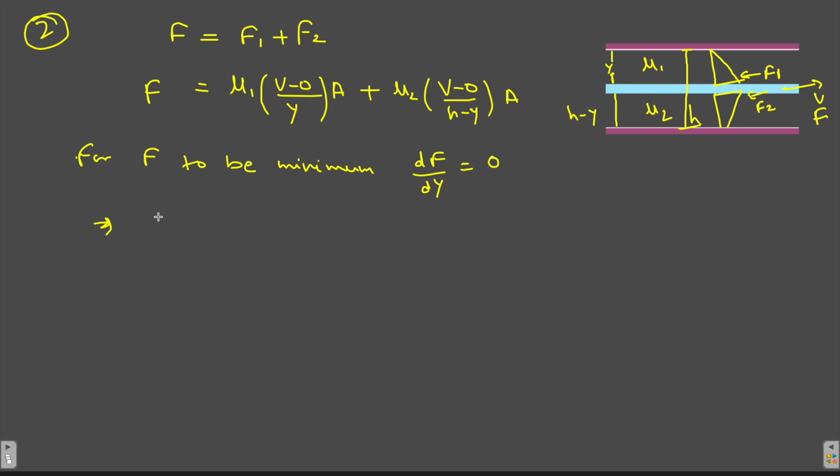So let's do that. So force is mu1 v by y into area plus mu2 v by h minus y into area, right?